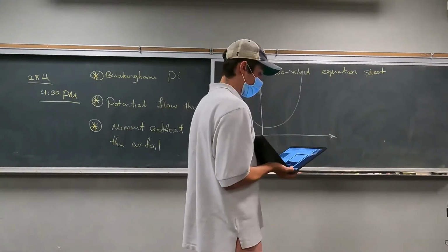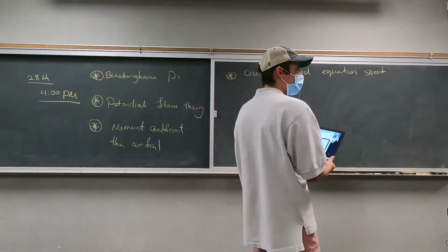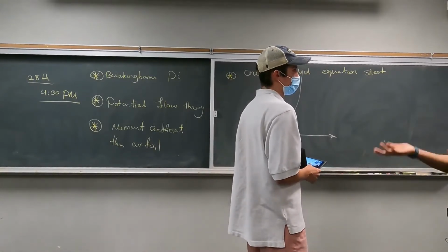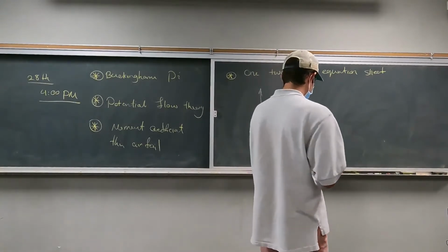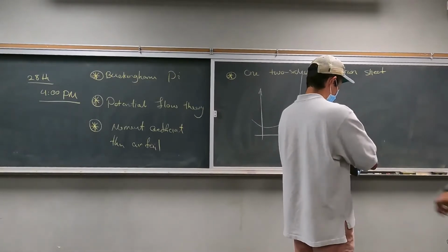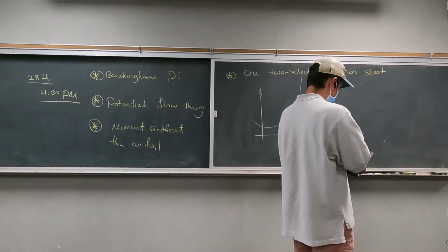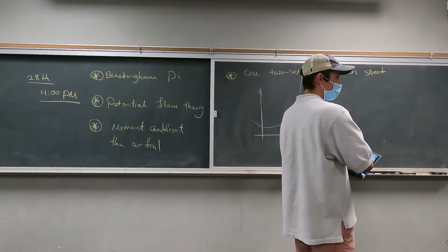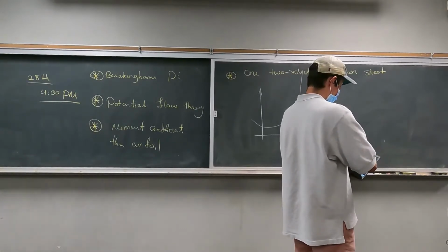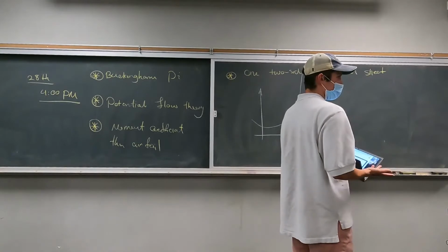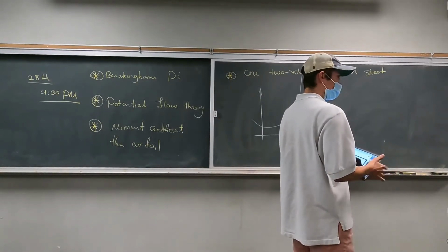So there's nothing really to compare. With thin airfoil theory, you can actually calculate drag, so it does exist in a sense. But there wouldn't be a chart like this for drag coefficient versus angle of attack. This is not a chart for thin airfoil theory. That is a chart for any airfoil. It's like comparing them to thin airfoil theory: theirs would be something like this, and then they would also have thin airfoil theory, so this is how it differs.